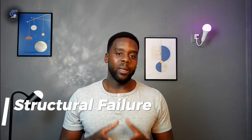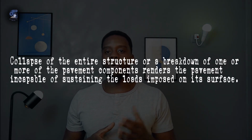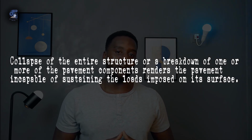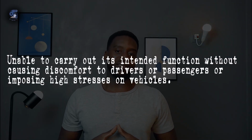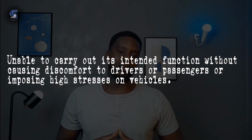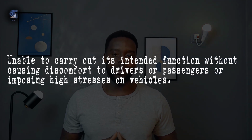There are two main types of pavement distress or failure. The first is the structural failure, in which the collapse of the entire structure or a breakdown of one or more of the pavement components renders the pavement incapable of sustaining the loads imposed on its surface. The second type of failure is functional failure, which occurs when the pavement, due to its roughness, is unable to carry out its intended functions without causing discomfort to drivers or passengers or imposing high stresses on vehicles.